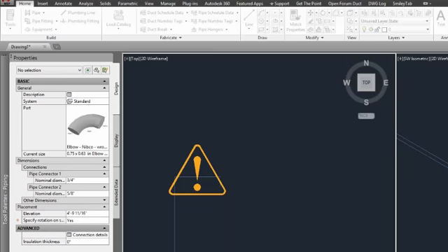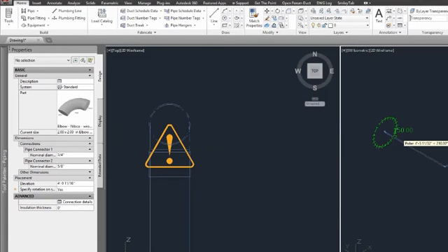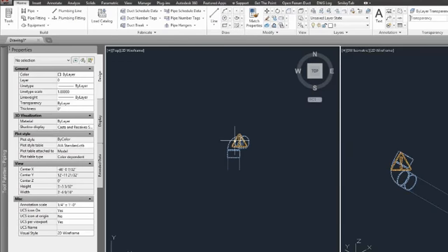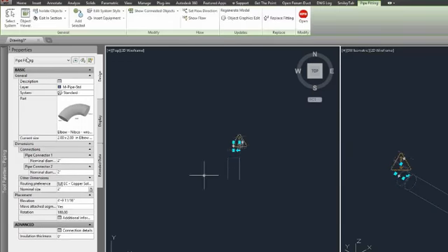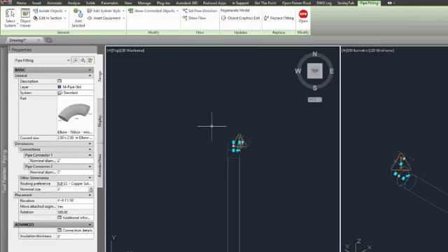And it's then going to ask you for a rotation value. And you can come over here into the 3D view and rotate it the way you want. So I can rotate it up 45 degrees. So on just regular elbows that you have in your routing preference, you can put them over here on your tool palette, but it's more preferable just to put the fittings that you won't use in a routing preference, such as street elbows, adapters, maybe some oddball couplings.